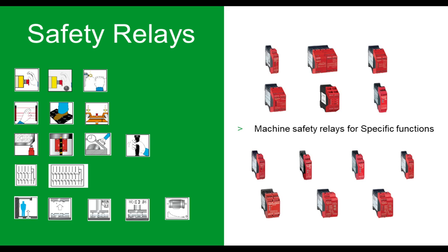So we talked about safety logic with programmable products, but just to be aware too, the reality is safety relays are what you usually see inside a control panel. So this is probably something like 70 to 80% of the time. If you open up a control panel, there'll be a PLC in there controlling everything, but there'll also be relays. And relays are very good. They don't have that kind of programmable logic capability, but some of the newer relays do have a little bit of logic in them, and sometimes it's enough.